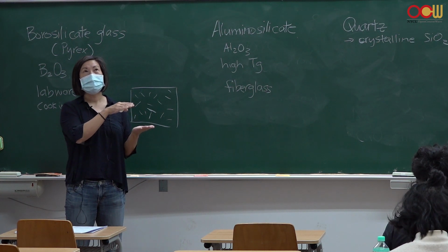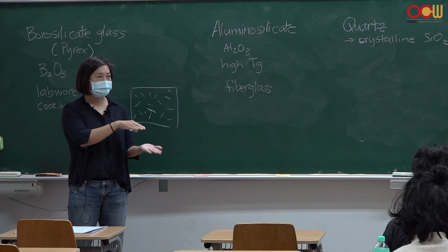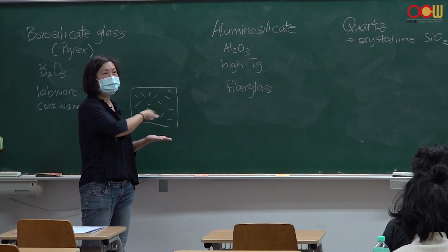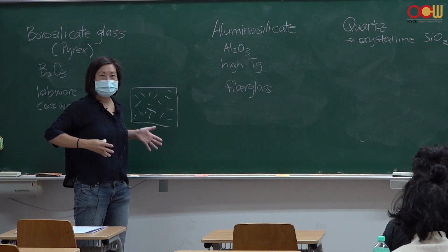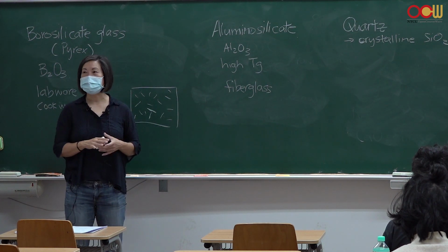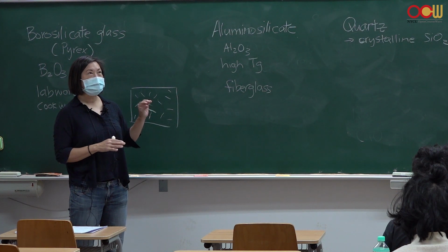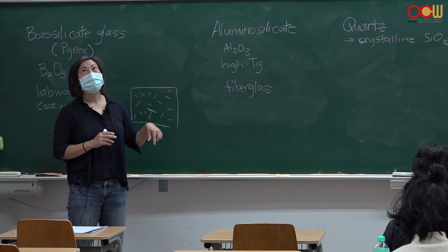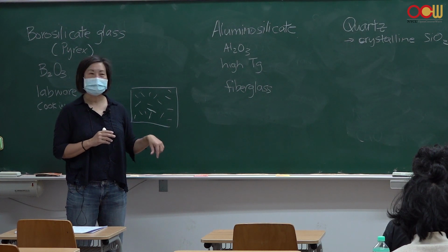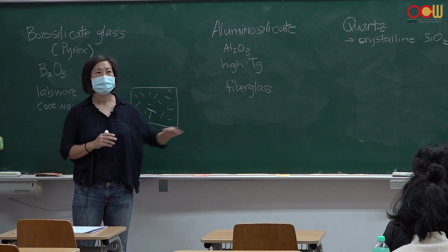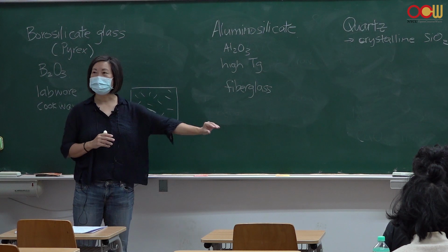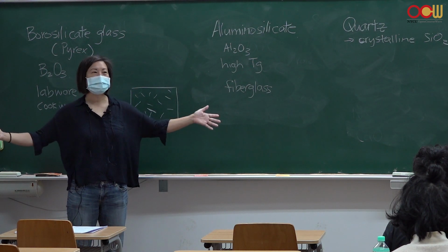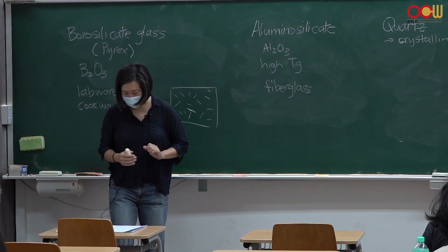So some sort of liquid metal that's very heavy, and then they can float the glass on top because glass is much less dense, and they can just let it cool that way. As long as the metal that it is floating on has a lower melting temperature than glass, the metal will stay liquid as the glass solidifies. Then they can make huge, huge pieces of glass that are perfectly smooth, and that's how they do it now.